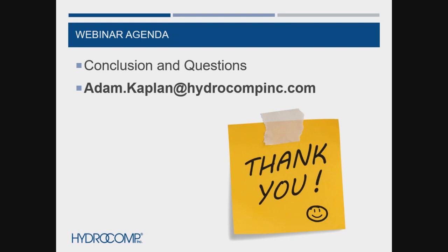Do you have an STL file size that you recommend? I have been using STL files between 50 and 80 megabytes generally. There's kind of a twofold issue with the size of the file. So you want to have a dense enough file that it very accurately represents the scanned geometry.